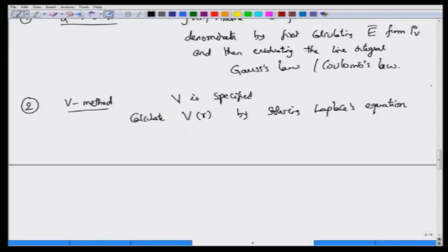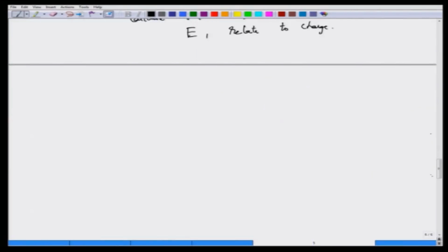From this, calculate the electric field, right. From the electric field, you relate this to the charge distribution, and then the charge to voltage ratio will give you the capacitance. Okay. We will see both examples in the following. Some of the examples will be simple because we use Gauss's law, and where Gauss's law cannot be used, this turns out to be a pretty hard exercise of computing capacitances if you do not use numerical methods.